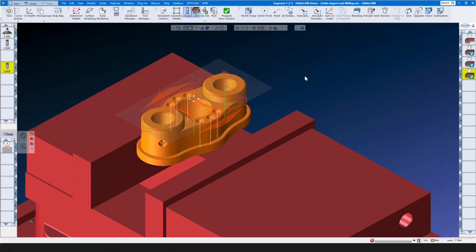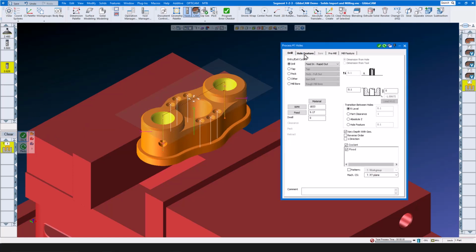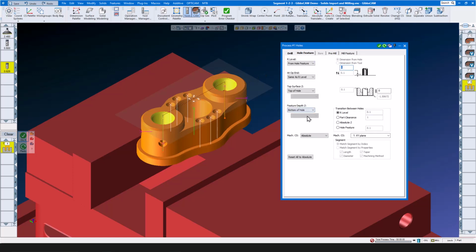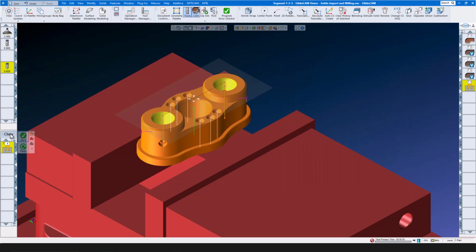The holes have now been highlighted, and we can click here and here to drill our 5/8 holes. Remember, this hole making process includes automatic functions that will detect the top and bottom of the hole. Let's do the same with the 1-inch drill.